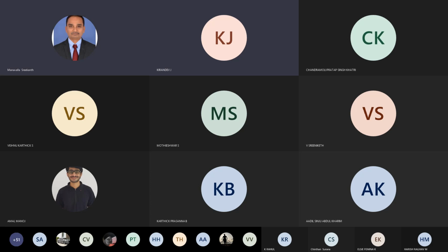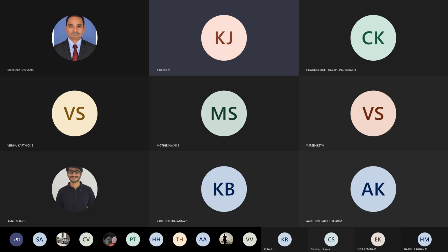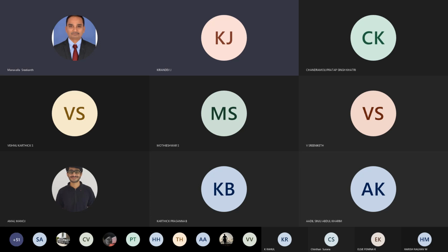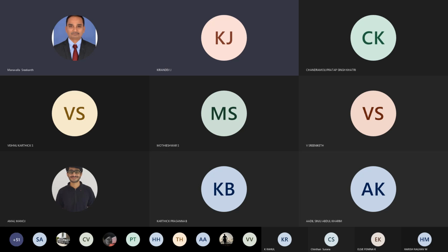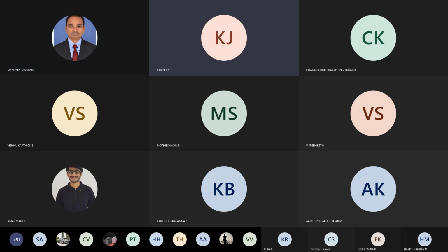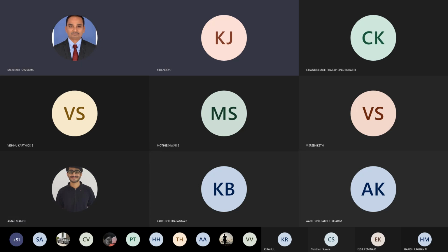But when it comes to radiation, we deal with the temperature raised to the power 4. There, by definition, the equation is in Kelvin. So there you will have to convert it to Kelvin. So if you have radiation, as I said earlier, better convert all the temperatures to Kelvin. Otherwise, you can take the liberty of continuing with temperatures in Celsius and still be correct. Okay? Yes, sir. But it's a good practice to always convert it to Kelvin.